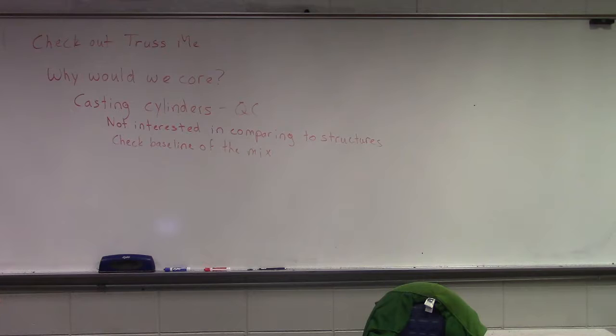So the last item on my mix design submittal is specifications. Dosage rates of admixtures may need to change. One of the things we can do is, if we know it's going to take us 20 more minutes to get to the job site and it's 90 degrees outside and sunny, with that sun baking down on it, burn it with a little bit more water reducer, right? If we're only using 3 ounces per hundredweight before, bump that up to 4 or 5 to help keep that mix nice and fluid for a while longer.